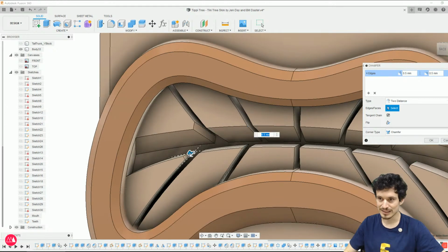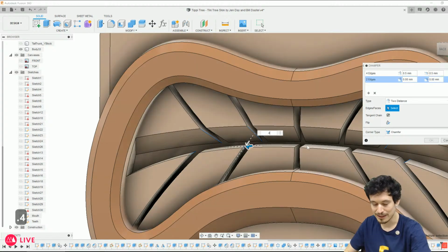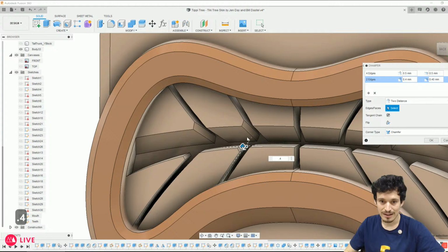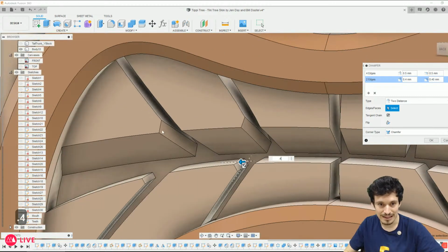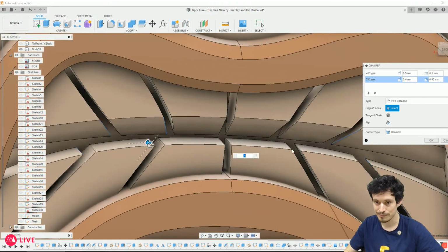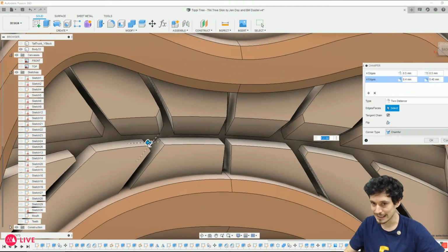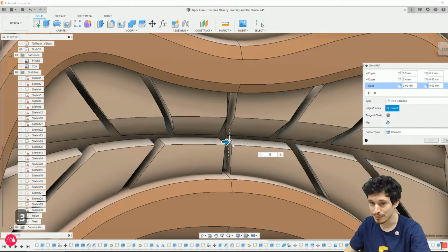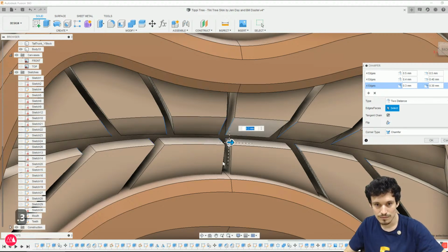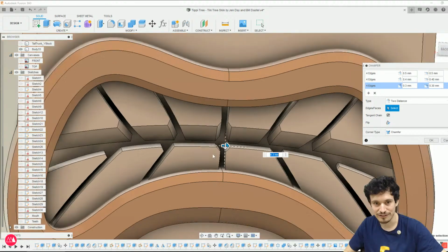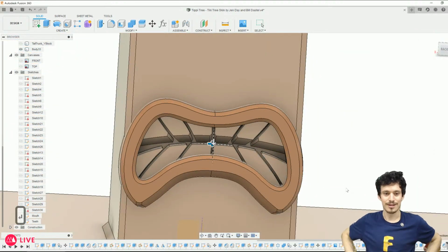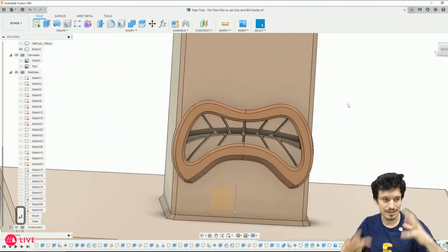This super steep one is going to be 0.5, 0.5. Then I'm going to add a new set for these ones and make those 0.4, 0.4. Smaller chamfer, but now if you look at the actual surface that it creates, it looks more similar. More consistent. And then for the final ones here, I can probably do 0.3, 0.3. Sure enough. Oh yeah, that looks good.